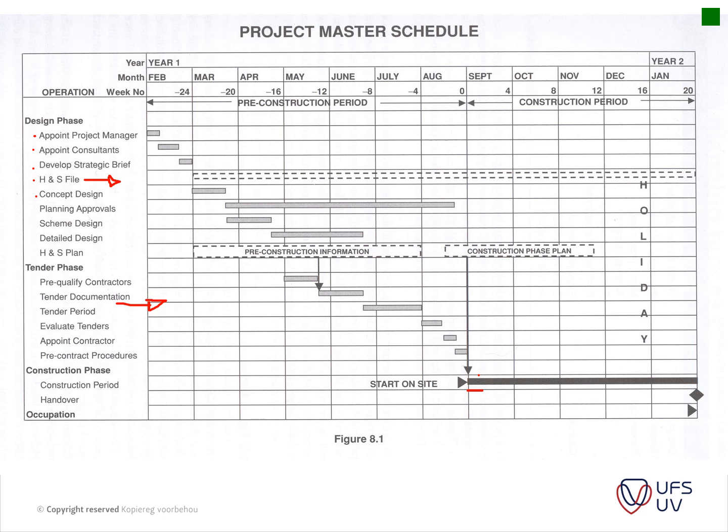The 2014 construction regulation says you have to have a health and safety professional appointed to do a baseline risk assessment and to assist with your design health and safety assessment as well. So that's something that you guys need to know, and it's usually difficult to bring that home to the clients because it does carry a bit of extra cost.